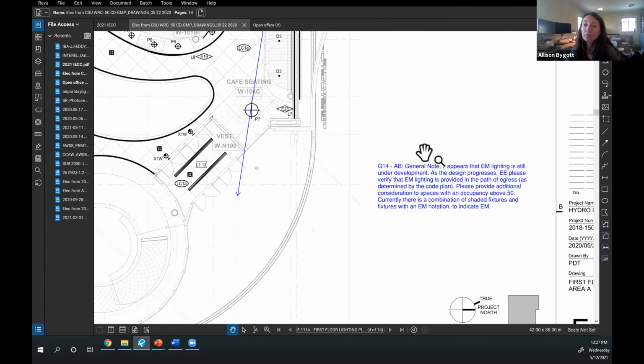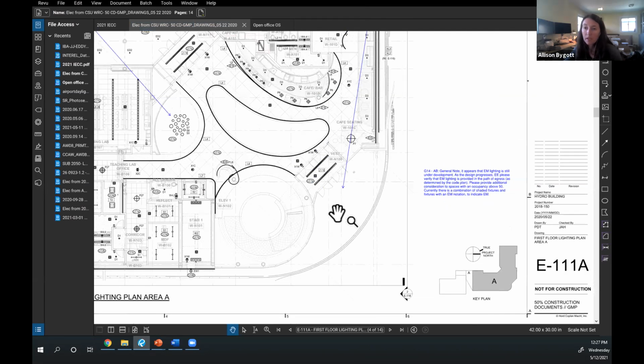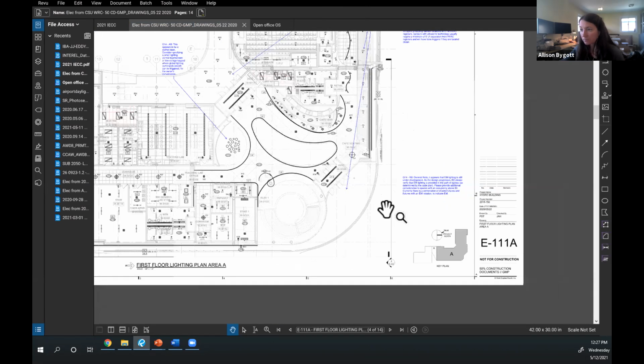But it's a really important piece of lighting control, because every time you have an emergency fixture in a zone, you need an automatic load control relay that's UL 924 listed so that it's forced on in an emergency. And those have to be coordinated. They are a piece of the lighting control system. They're either standalone or they're relays in the lighting control panel.